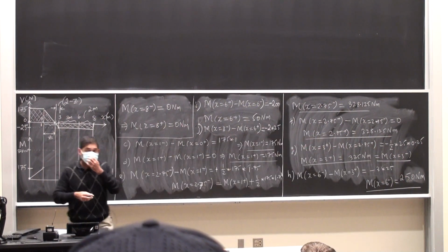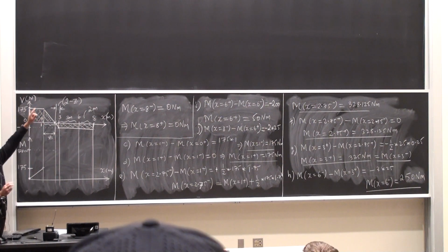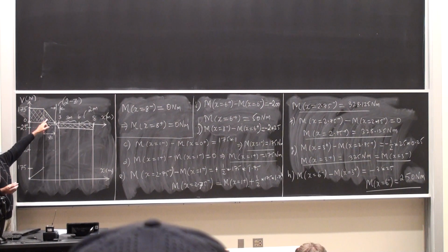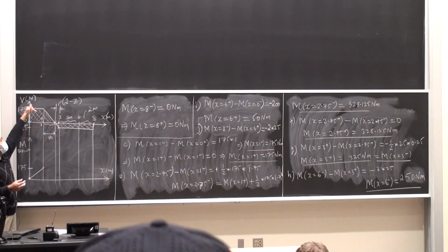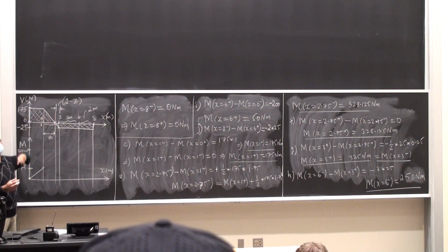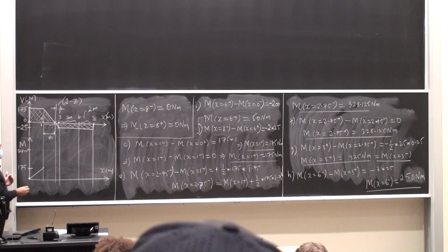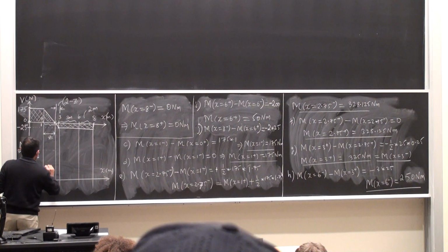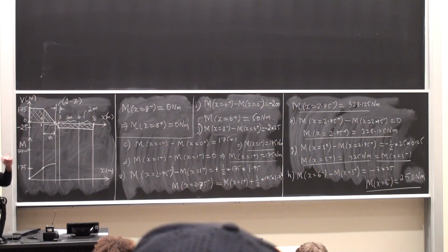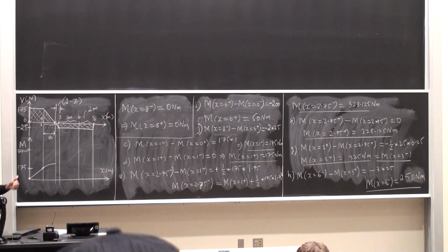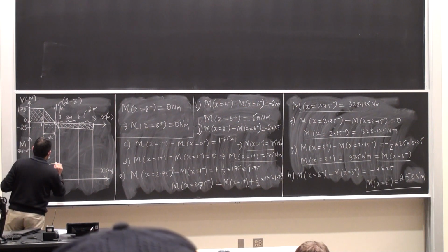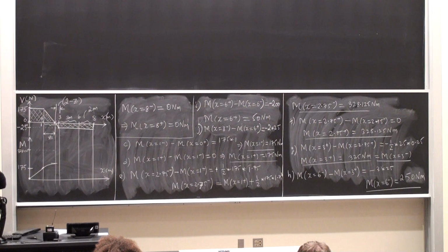Okay, so here's what happens. Slope of the bending moment diagram is equal to the shear force value. The shear force value is positive but decreasing from 1 to 2.5. So which means the slope of my bending moment curve should be positive and decreasing. So I start off at the slope here, that has to be continuous, and then I draw it as a quadratic. Okay, this is a quadratic. Ends up as a 0 slope because the value of the shear force becomes 0 at that point.